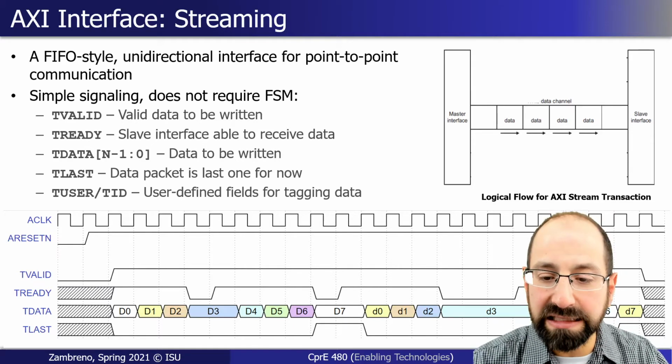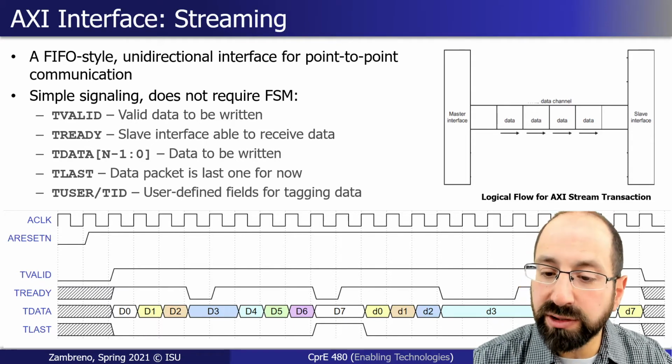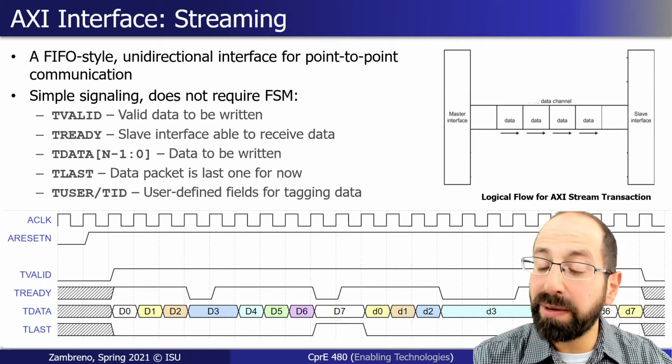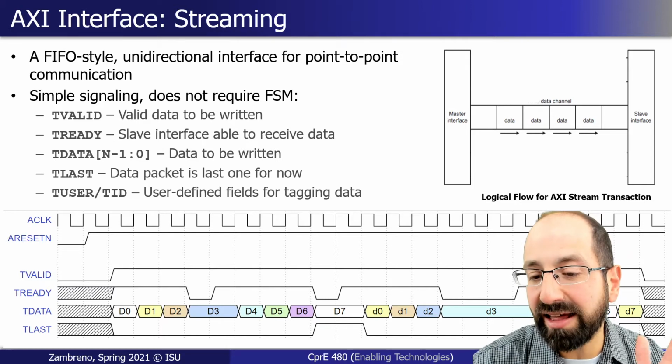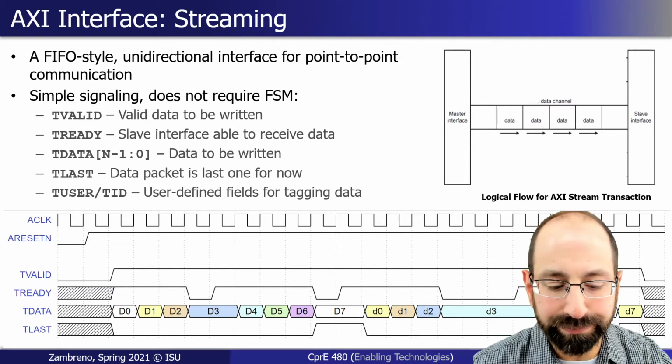Same with T user and T ID. We get to decide if we want to use those signals for anything. The spec works just fine if you're not using them at all. So you really just need ultimately T-valid, T-data, and T-ready.